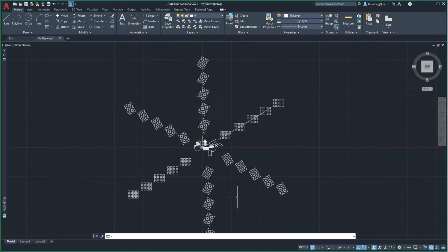At the prompt of Select Path Curve, select our new line and press Enter to exit the command. Again, within the squared brackets were several command options, and post-creation, there are many adjustments the user can make to this path array in the Properties palette.